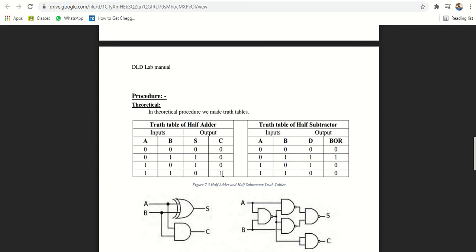If we go to more bits, we will have more carry, and therefore carry is there for the adder. Okay, so we understand what the carry is here. The carry is the number that comes in the result of addition, when we have a number like 1 1 and it gives us 1 0, that is 2 in decimal, so we will have a carry in here and the sum is 0.